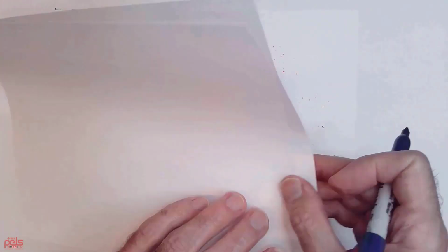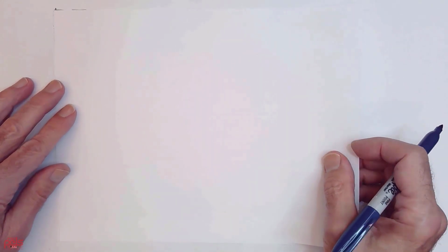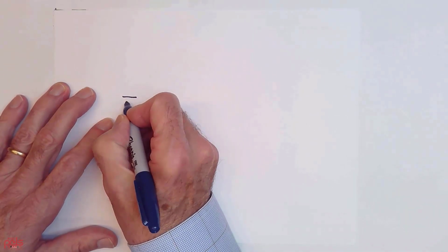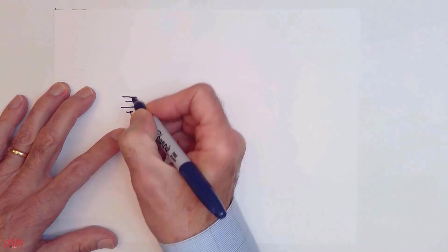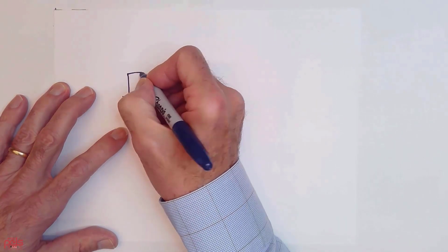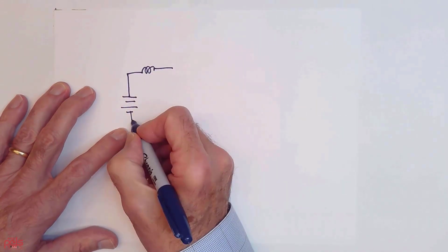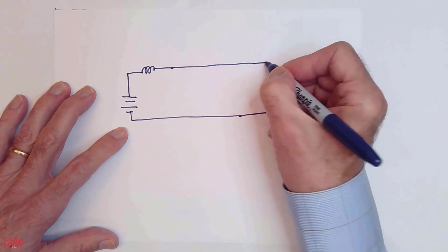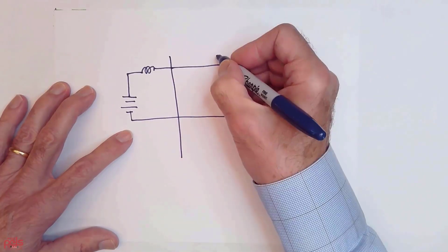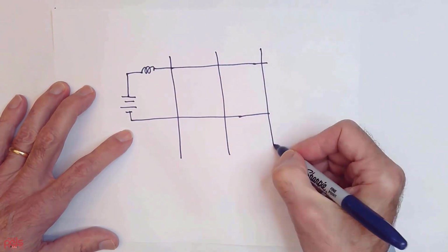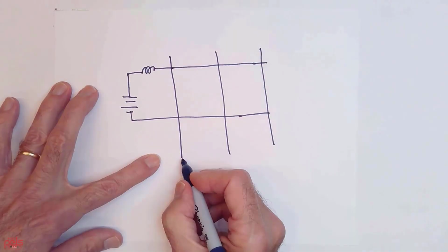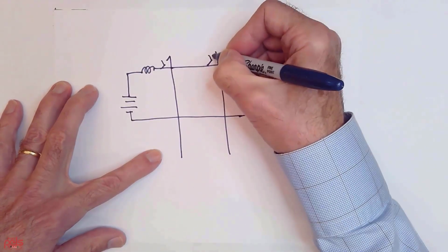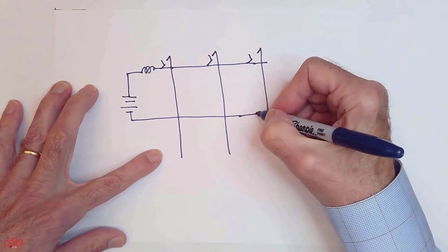Okay, this becomes important. So what happens at my input? Well, maybe I don't have a DC current source. Maybe I have a DC voltage source, and I'm going to put that in series with an inductor. All right. And I have limited confidence that my output is really a completely stiff voltage source.